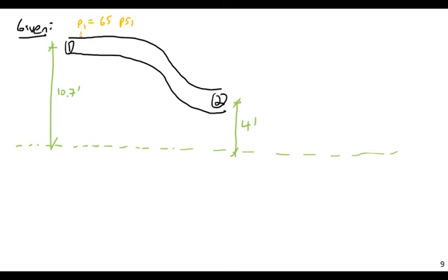and D1 is 6 inches. And I'm also told that Q1, the flow in, is 2.08 cubic feet per second, which also means that Q2 is equal to the same thing. As long as the fluid is incompressible, I immediately know that the flow rate over here is also 2.08 cubic feet per second. I can trade area for velocity, but flow rate, at least for an incompressible fluid, is going to remain constant.